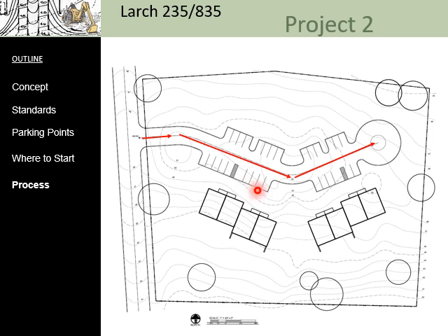You're not going to worry about designing your sidewalks yet. And then you're going to say, from there, I need to get to the building. And you're still going to target 2% to get to that building. So ideally, you're going to start in the center at some point. You're going to go up or down 2% to get to the curb, jump up 6 inches, and then also use 2% to get to the building.